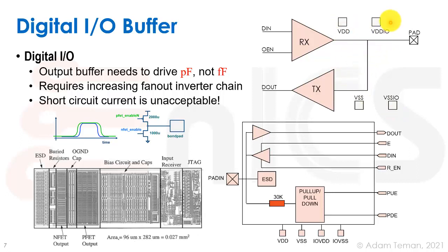Well, mainly because the I/Os, when we drive an output bus, are going to need a lot of current to go into the large capacitance we have outside the chip. So the need to drive that current is going to cause a lot of current pull from the VDD, and that could impede the level of the VDD that's going inside the chip. So that's why we separate them.